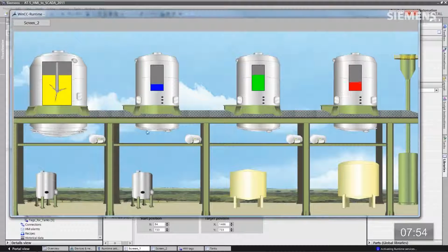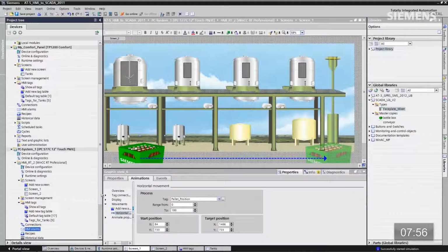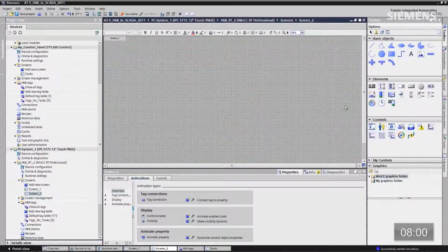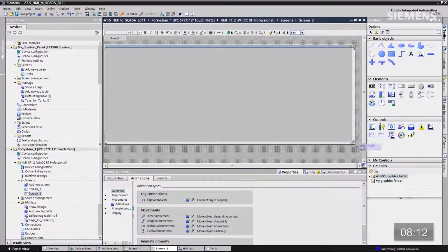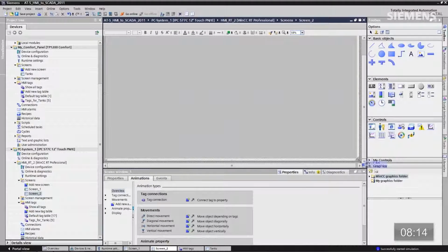However, there's one other thing I want to show you. How about actually doing a screen-in-screen or pop-up technology? So let's go to screen 2 real quick. Double click on it, and let's go grab the control icon for this. It's called Screen Window. Let's drag it on. This is the ActiveX control. You can see a little alignment bars just like in PowerPoint. That way you can align your boxes wherever you want to and get everything sized right. Let's resize, refit them on to the screen.